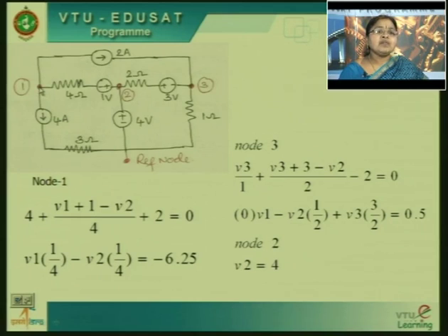We are saying that V1 is at higher potential, some positive voltage is there. This positive voltage is connected to the negative of one more source. That means this voltage is aiding this node voltage V1. So, if the negative of the source is connected to V1, what I should write is V1 plus 1 volt, because that is adding to this node voltage. That is why the equation V1 plus 1 minus V2 divided by 4 gives me the current flowing through this branch. Is it clear?